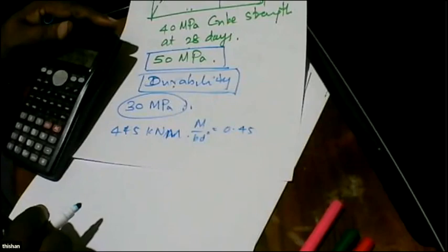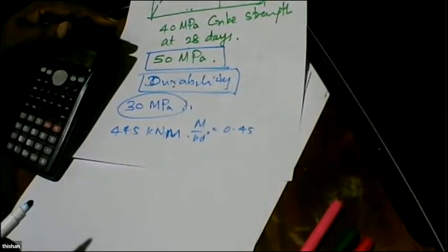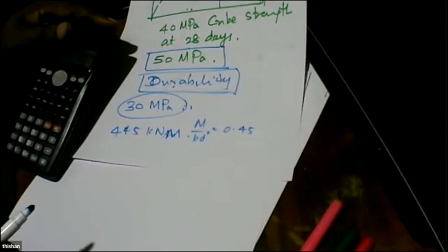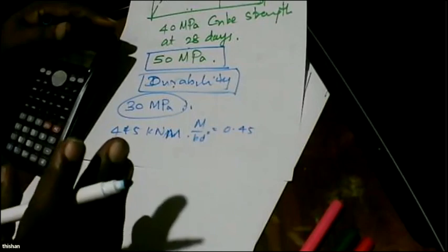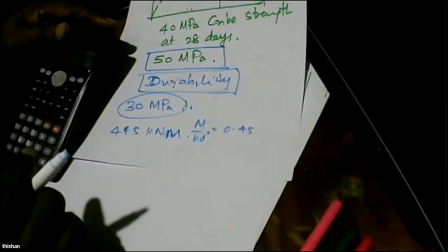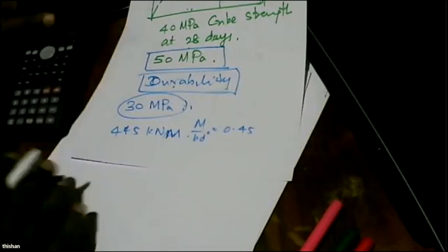Because of that reason, it has a huge capacity, because this beam is going to behave as a flange beam for live loads. So when you look at this number, strength of concrete is not important when you are deciding the amount of reinforcement. It's going to be the same amount, right?